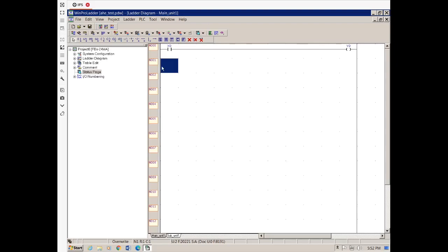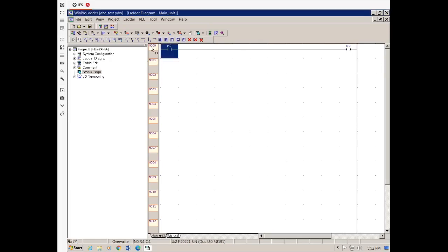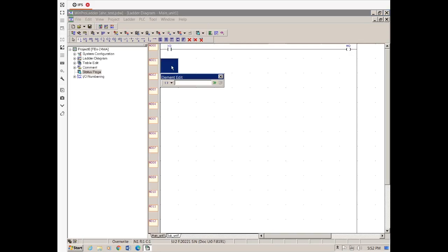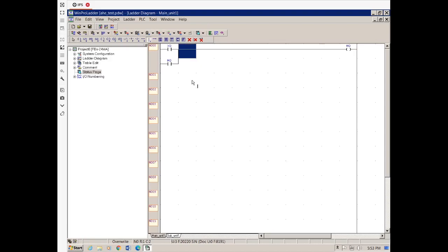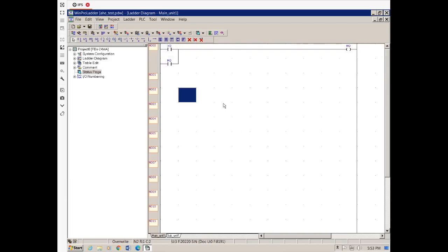Now moving on, latching also works similarly. Just to show you that latching works, I can quickly rename this to a memory location. In order to use a latch, I can get that same memory, so what we need is actually the same X0, and in addition we need to add another memory location here, M0. Then we can connect a horizontal and vertical line. Once you connect that, automatically the rung will be expanded. That is how this interface works.